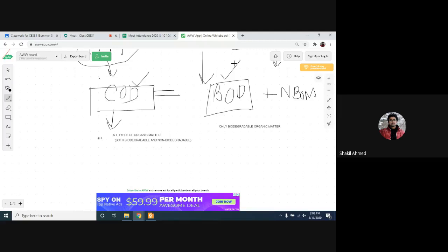COD. If NBOD is 0, then they might be equal, COD equals BOD, but COD cannot be less than BOD. COD has to be greater than or equal to BOD.